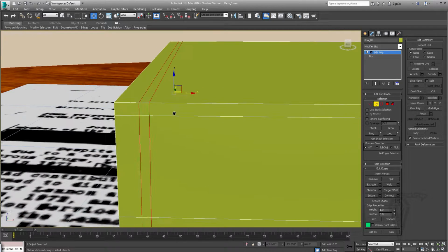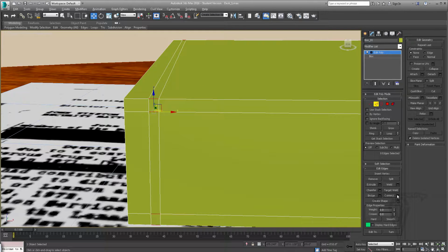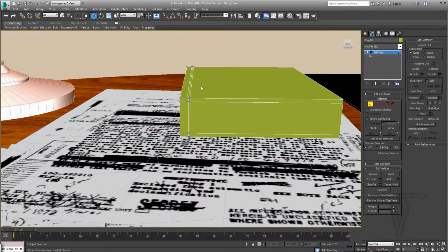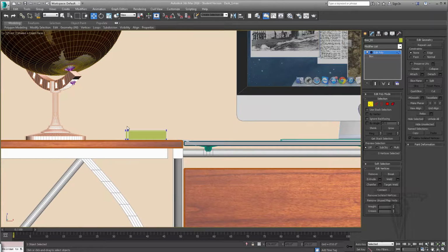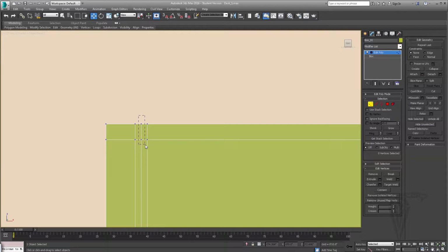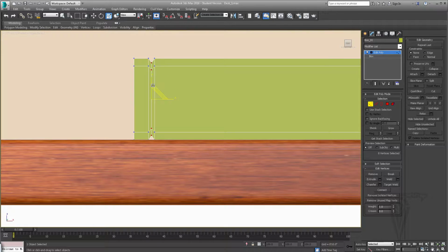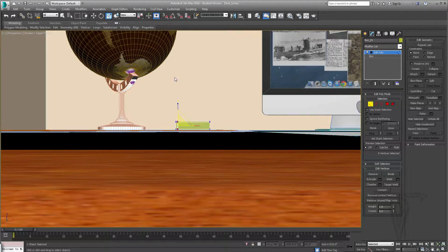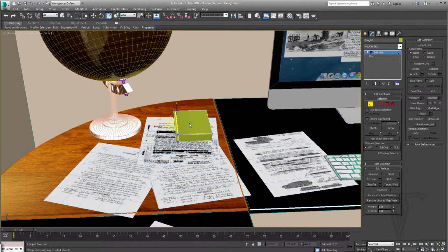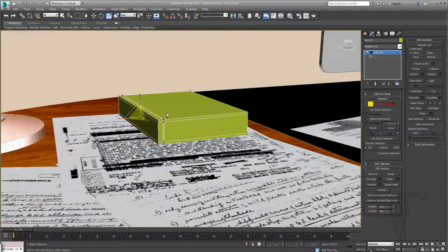Okay. So I'm going to do one more edge. Click this, ring, and connect. Set everything down to its base. So 1, 0, 0. Check mark. So I'm going to go to vertex mode. And let me go to the front view. I'm going to drag select over these 2 vertices and drag select over these 2 vertices. Use my scale tool, scale them down a little bit. It's probably too much. Something like that. P on the keyboard for perspective. Z to zoom extent.